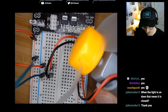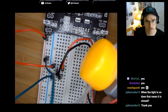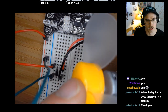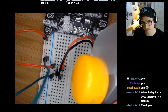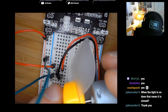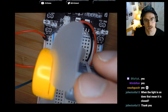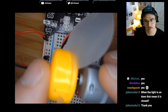And so we're going to be turning on and off this relay. So we're going to be turning on the motor, building up a magnetic field, and then when we turn off the motor, the current running through the motor abruptly drops to 0 because the circuit gets disconnected. There's no current flowing. Well, when you abruptly disconnect the current to a magnetic field, it generates a big voltage spike.